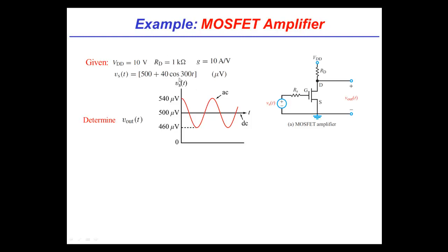So we'll go ahead and set that up. So here's how I'm going to cheat. I will first pick, this is the circuit I'm going to use, but I'm going to pick the values to ensure that I live in saturation. Now, when we talked about this, Michelle, what was the key to living in saturation? Well, I think we want our VDS to be pretty large, right? Right. We want VDS to be pretty large, and we want VGS to be large enough that the transistor is on. That's right. We want to keep it on as well. So two constraints: make sure VDS stays large and make sure that the transistor is on.